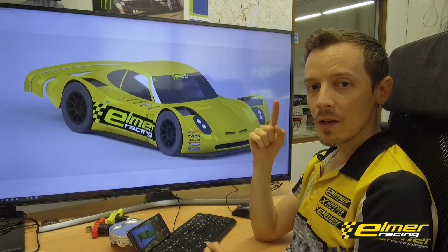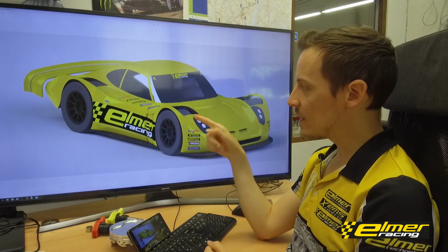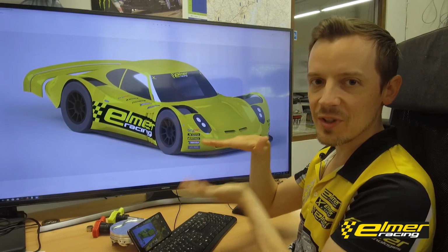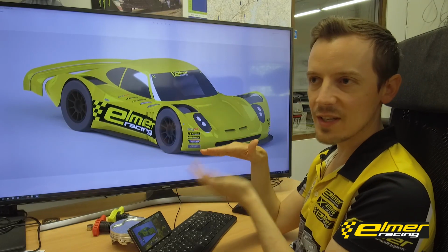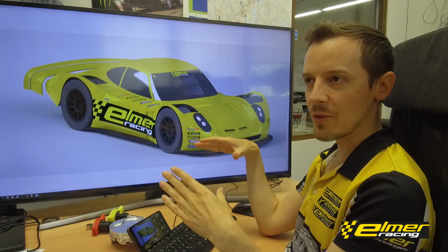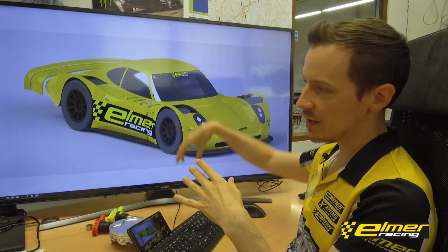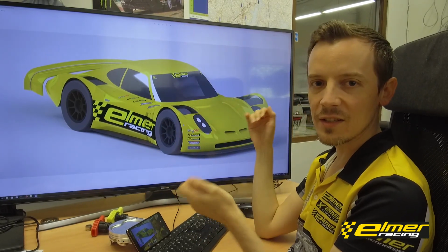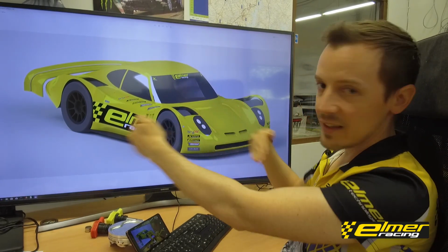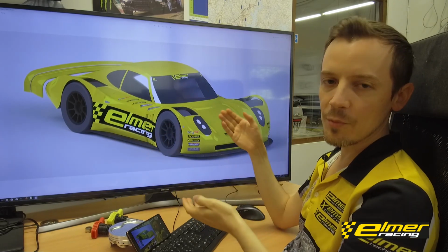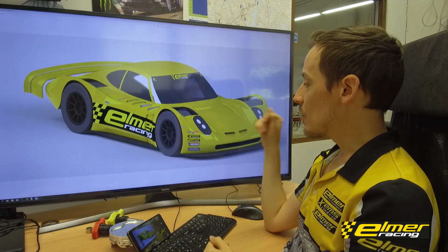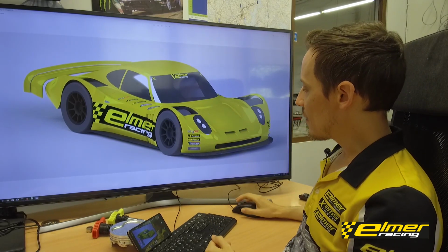But another aspect of creating downforce. Downforce is created by pressure differences between the top and bottom surfaces, and when you have a pressure difference, you have the surface area of that, or the surface area projection in the height dimension. Let's call that the z direction. So the larger the width and length of the area that you're creating the pressure difference over, the more force you will have for the same pressure, of course. So you want to maximize that surface area.